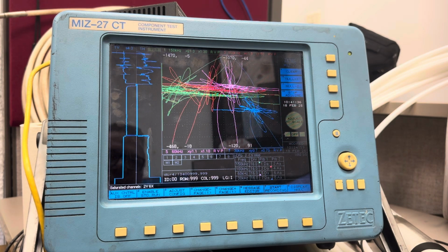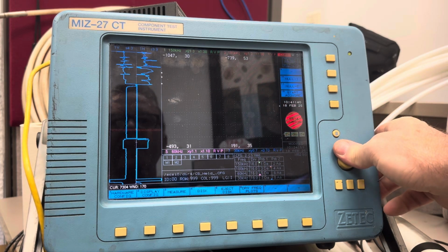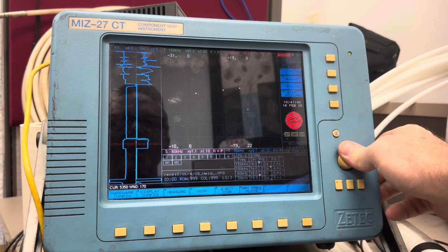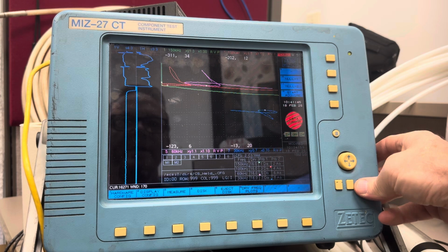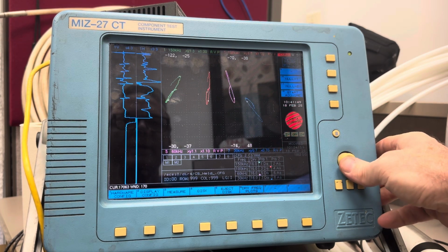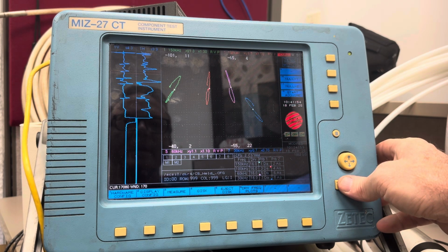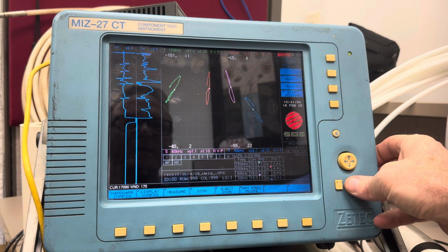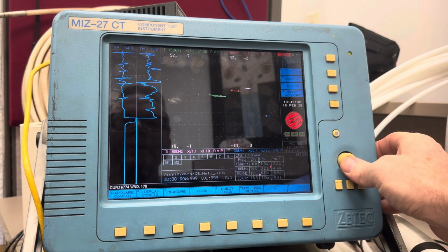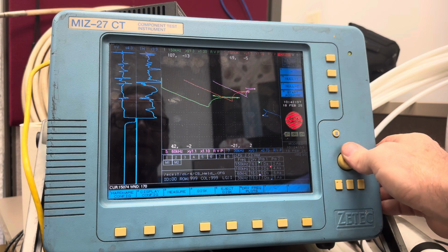We got a bunch of signals there. So now I hit Stop Acquire. And this is always how you analyze bobbin data if you're doing it the right way. You do it once the entire tube record has been recorded, so you can take as much sweet time as you need to do a thorough and complete analysis. So what I've done here is I've already rotated my signals.